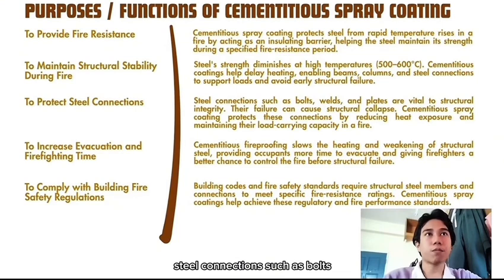Steel connections such as bolts, welds, and connection plates are critical components of a steel structure. Failure of this connection can lead to partial or total structural collapse. Cementitious spray coating protects this connection by reducing heat exposure and preserving their load carrying capacity during a fire.